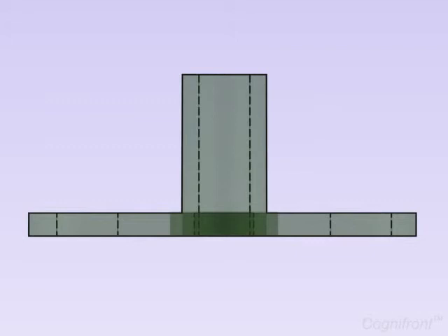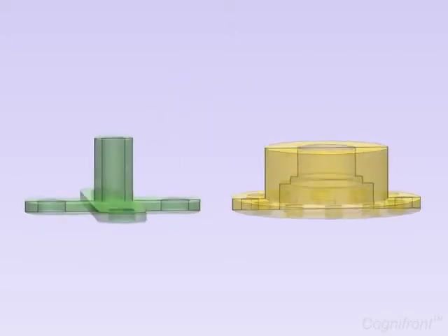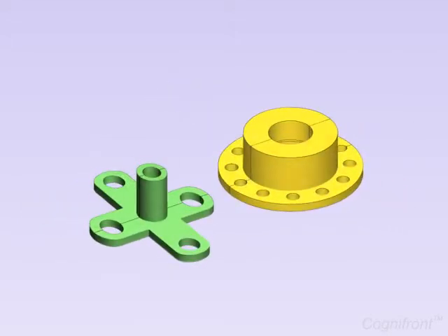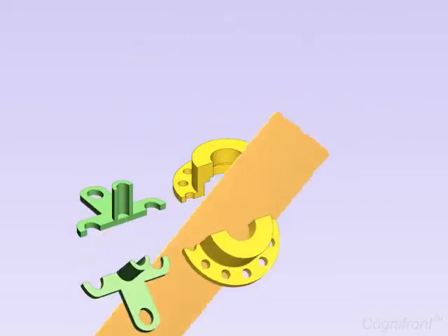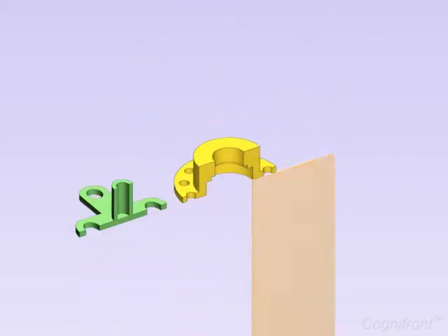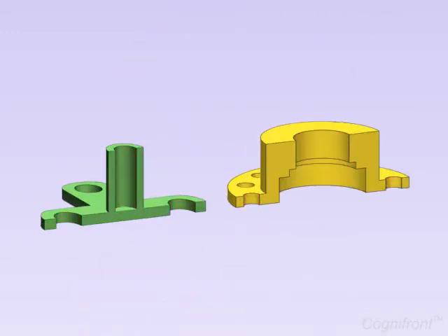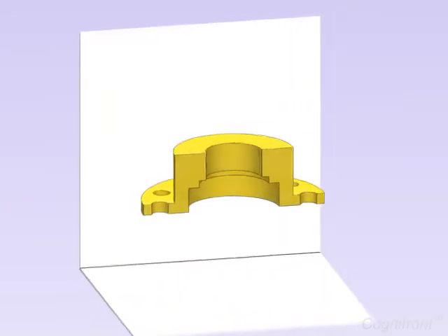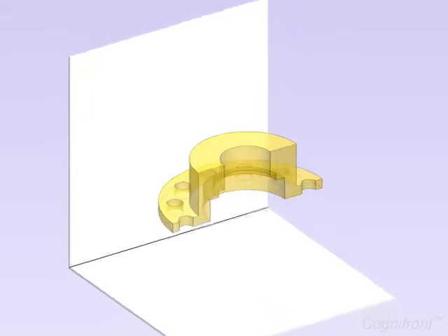In such cases, usually it is assumed that the object is being cut by a flat cutting plane, exposing the hidden features. This process is known as sectioning, and the views exposed by cutting planes are known as sectional views. These views are obtained when the exposed portion is projected on any of the reference planes.